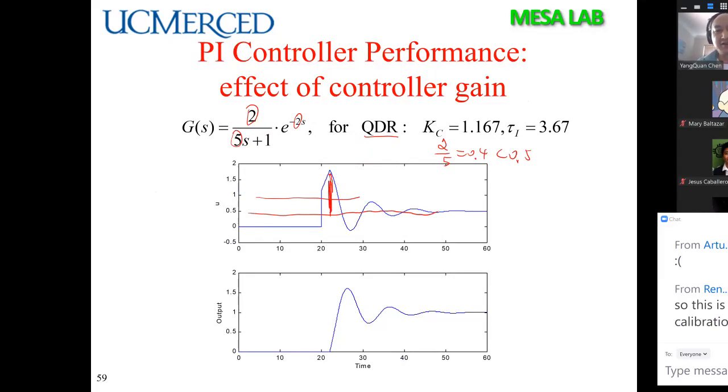This divided by this is the ratio, a quarter damping ratio. This guy divided by this guy is 4, so 1/4. After the second peak, you damped 25%. So this is a QDR. That's the meaning.